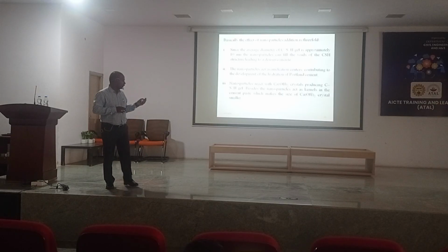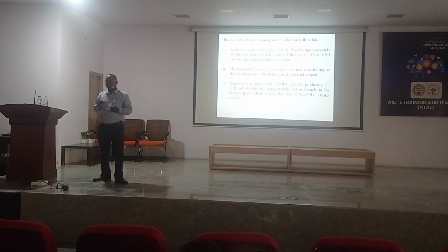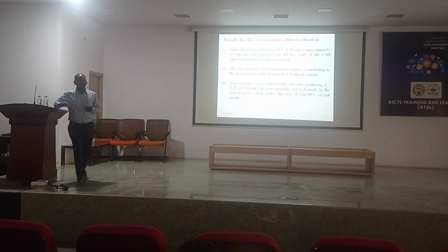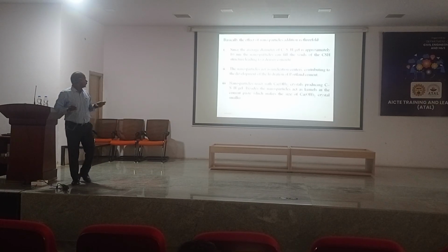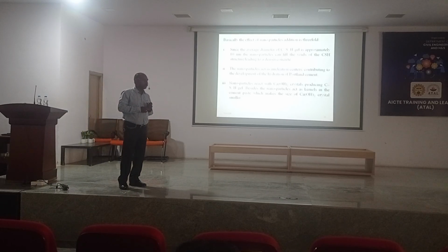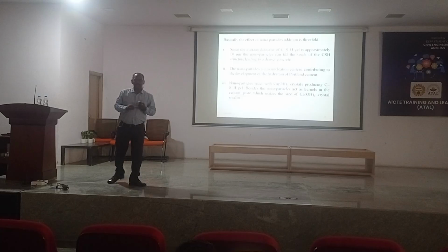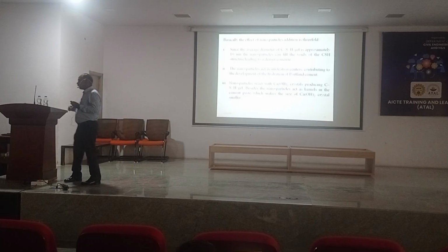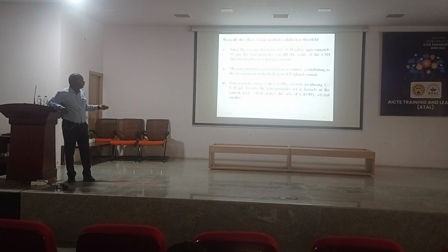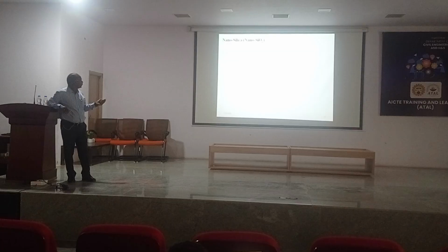These are the main three advantages. One is nano voids can be filled with nanomaterials. Second, these nanomaterials will act as nucleation centers and improve the hydration process. And third, these nanomaterials also react with calcium hydroxide and reduce the amount of calcium hydroxide. These are the three advantages of adding nanomaterials in the cement.